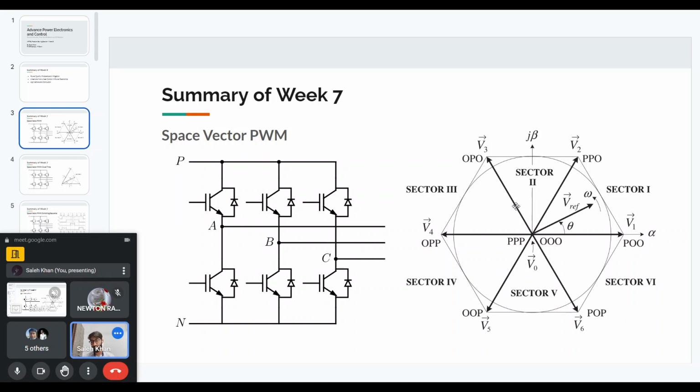If we want a rotating magnetic field, we can divide it into these 3 currents that are spaced apart. Similarly, if we have a Vref voltage that we want at the output, we can divide it into its equivalent 3-phase components.